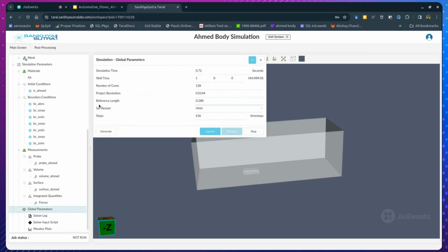So set restart essentially is the same feature that I explained about before. It enables the user to save states of their simulation at certain instances of time. There are two ways in which you can specify the frequency of saving these instances. You can specify them both in terms of steps or iterations of the simulation, or in terms of gap, that is in terms of seconds within the simulation space.